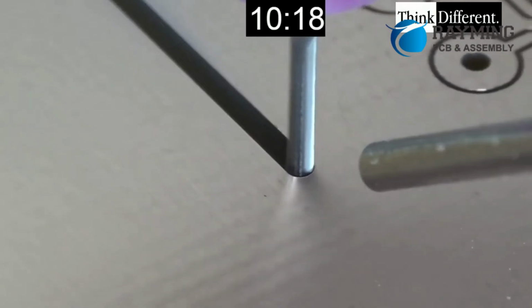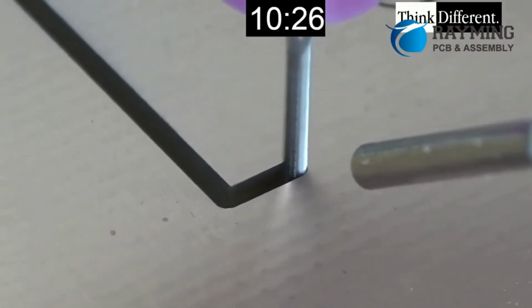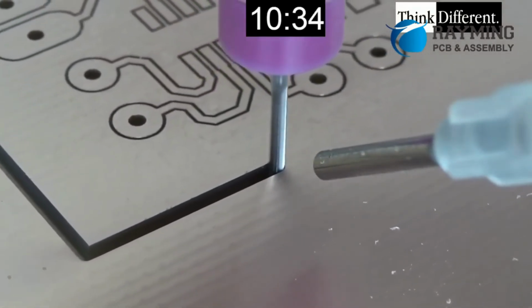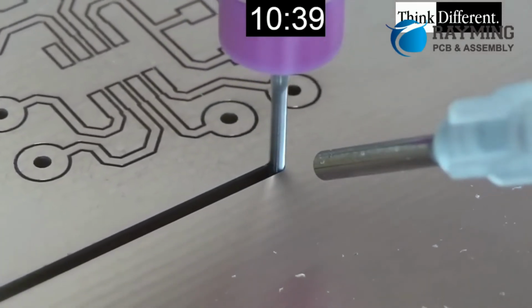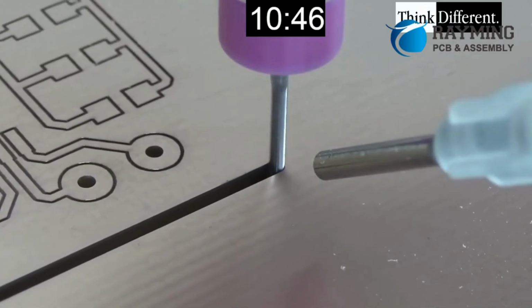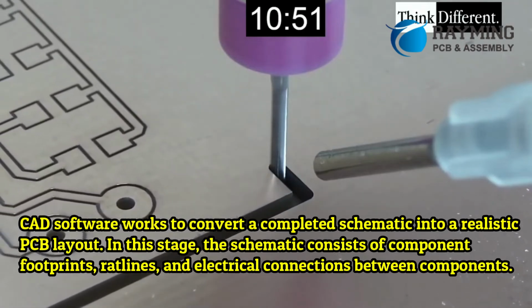Before starting the layout process, it's a good idea to review your PCB schematic. It will likely undergo several revisions before going into production. Checking it now can help you avoid surprises during the board layout. In addition, it can help you find duplicate circuitry and parts that you may have forgotten to remove. Regardless of your background in electronics, you'll benefit from the extra attention to detail. Besides that, a PCB schematic is a great way to avoid rushing through a design stage if it's not completely final. CAD software works to convert a completed schematic into a realistic PCB layout.